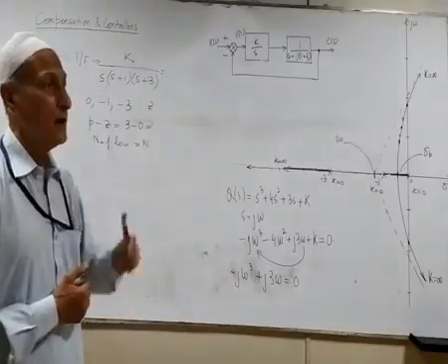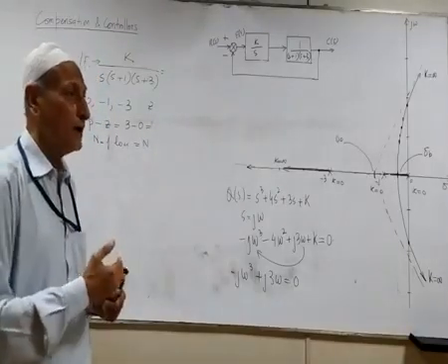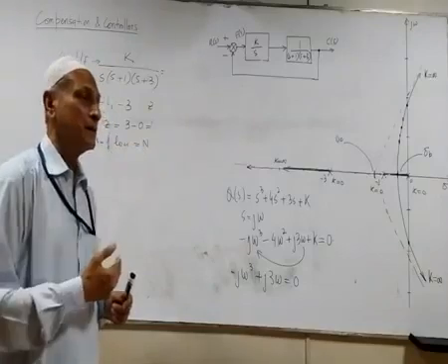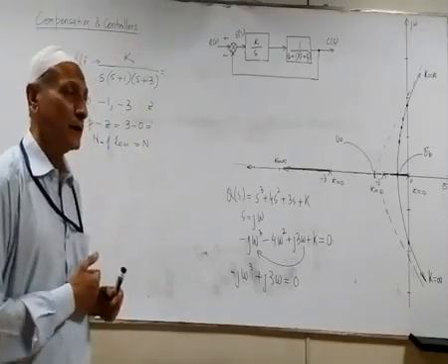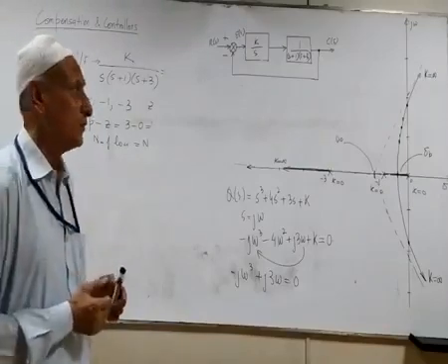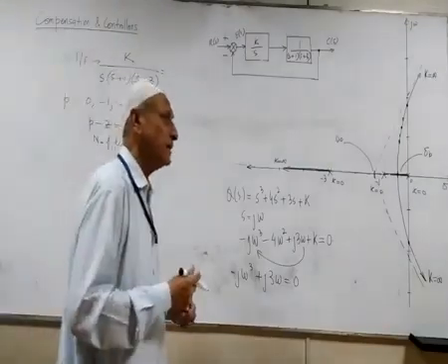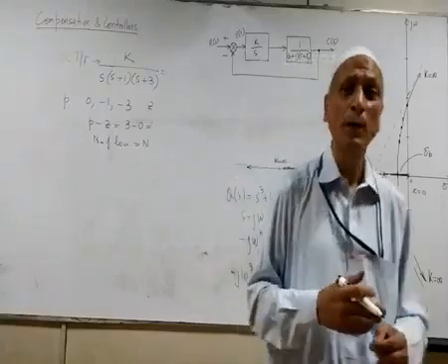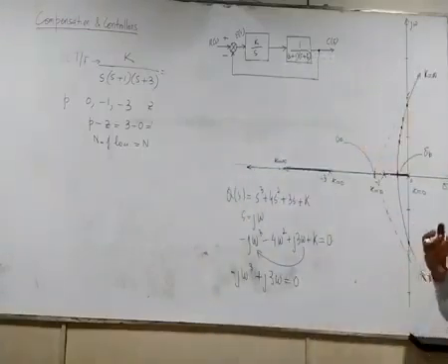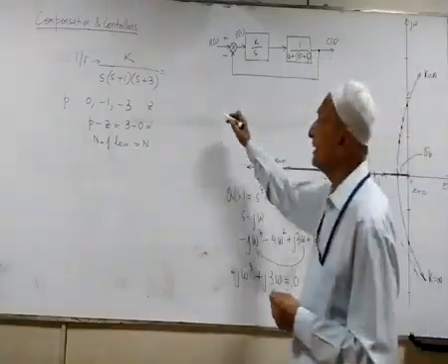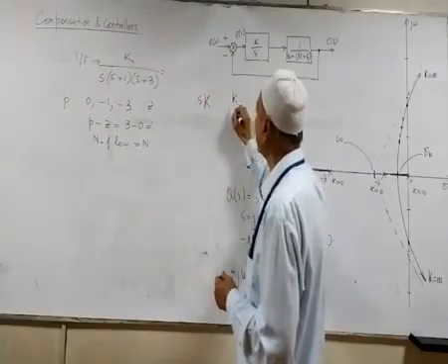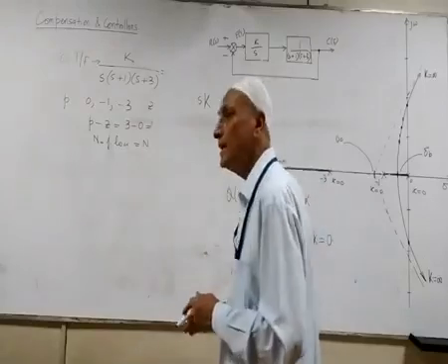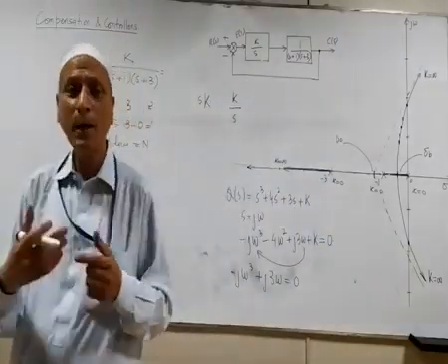But you are putting right the steady state response. You are improving the steady state response. However, one thing you must note, and it is worth mentioning, is that a simple gain pure derivative controller and a simple gain pure integral controller are not practically available.